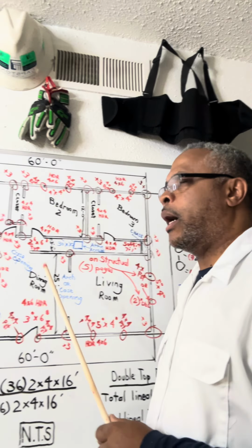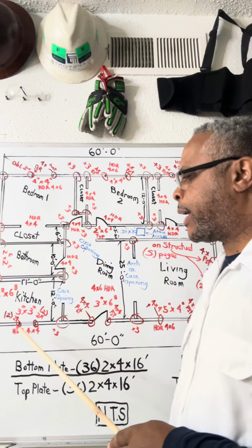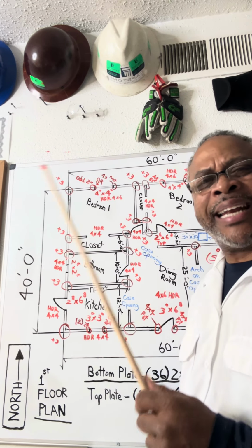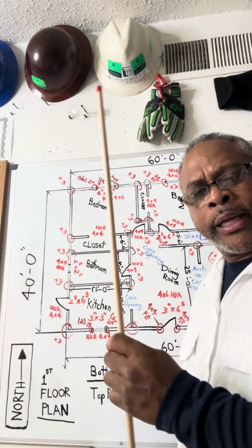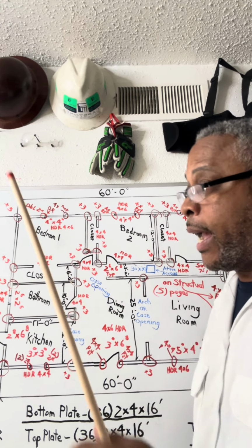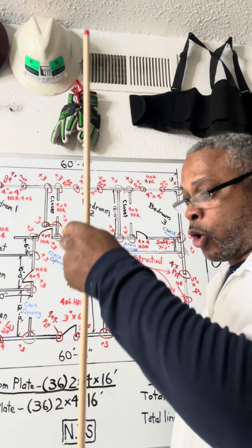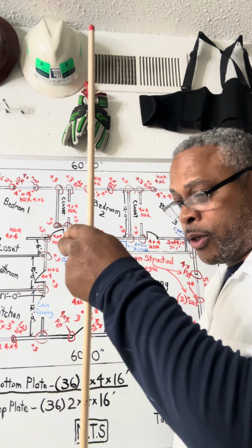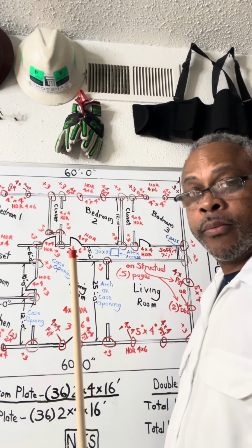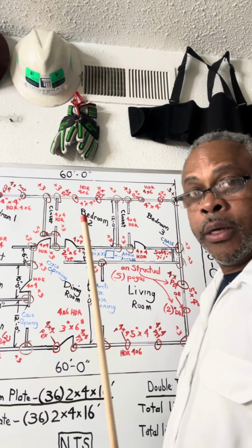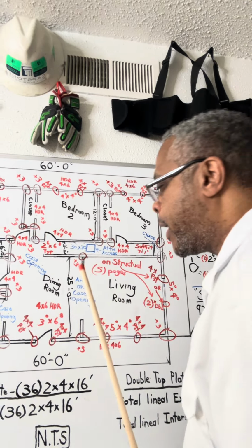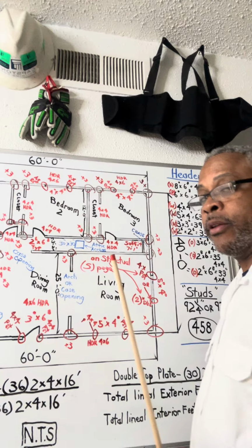You have your back door sometimes. I could take this kitchen door and put a French door there, which means they have panes, like lights, which means there's wood in between and it's separate. French doors are expensive, okay? And the glass goes all the way from the top towards the top of the door, several inches down, to the bottom of the door, several inches up. And it's a grid system for that French door. Mostly has to be stained. They could be painted, mostly stained. Very expensive door to hang. They're very heavy too as well.